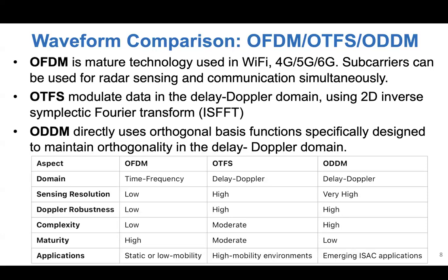And we know that for a square wave, the pulse shape is a square. If it's square in one domain, in the other domain it's a sinc function, right? The sinc function will have very bad side lobes. So even though the story I mentioned for delay-Doppler is very ideal, if you're using OTFS, this side lobe interference will be everywhere in the delay-Doppler domain. You cannot have too much resource allocation, because when a user is there, the leakage will be everywhere.